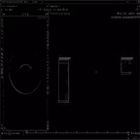So what are these? These two default nodes are in charge of reading data from the incoming geometry and writing data to the geometry that is currently processed. This here is a point VOP. That means whatever you do here inside of this network gets executed for every point of the object that is connected to the input port. These ports here are the different informations you can gather from the incoming geometry. The names are abbreviated. You have some learning to do here. You have to just remember what all this means, because nobody is telling it to you.